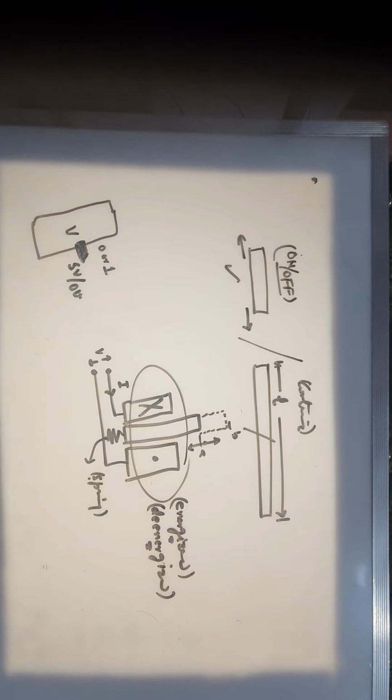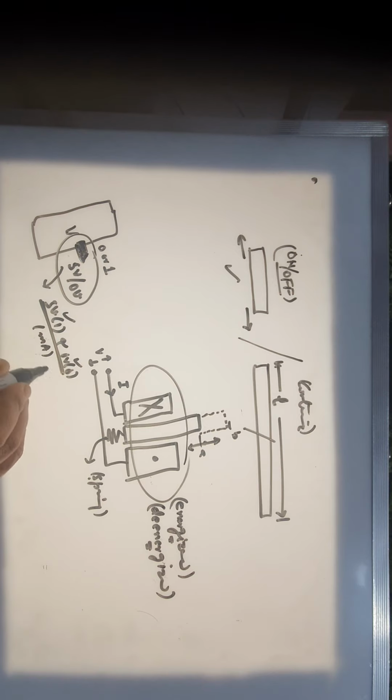But that's not possible, because in all the processors that we use, the pins can provide you 5 volts at logic 1 and 0 volt at logic 0. But the maximum current that they can source or sink is in milliamperes. That too, not more than 40 milliampere.